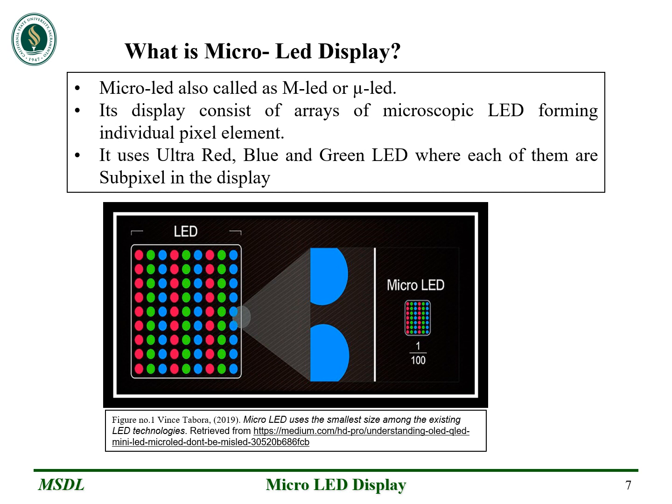Now, what is a micro LED display? Micro LED, also called MLED or µLED. A micro LED display makes the LED structure thinner, smaller, and arranges it in an array. Individual micro LEDs usually range from 1 to 10 micrometers and are transferred in large volumes onto the IC substrate. The substrate can be hard, flexible, transparent, or non-transparent. By using physical vapor deposition to complete a protective layer and form the top electrode, it can be packaged into a simple-structure micro LED display.